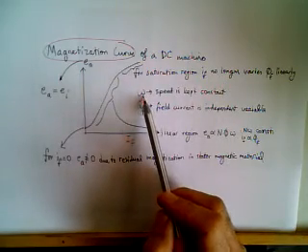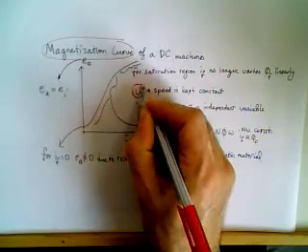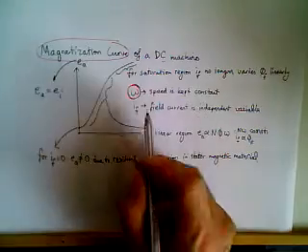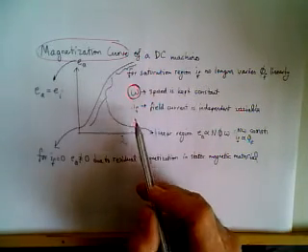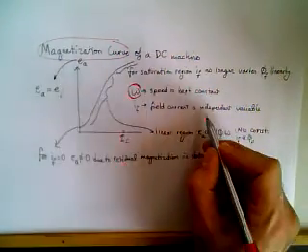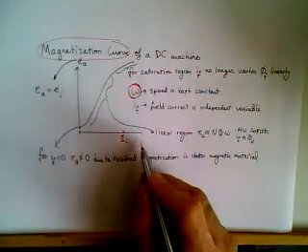This curve is obtained under constant speed, so during the experimental obtaining of the magnetization curve, omega is kept constant, and IF, the field current, is our independent variable, plotted in the horizontal direction.